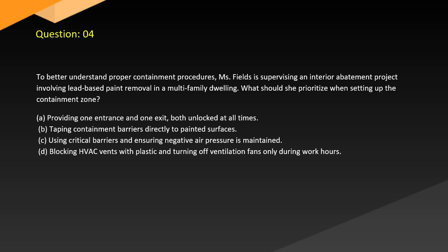Question 4. To better understand proper containment procedures, Ms. Fields is supervising an interior abatement project involving lead-based paint removal in a multifamily dwelling. What should she prioritize when setting up the containment zone? A. Providing one entrance and one exit, both unlocked at all times. B. Taping containment barriers directly to painted surfaces. C. Using critical barriers and ensuring negative air pressure is maintained. D. Blocking HVAC vents with plastic and turning off ventilation fans only during work hours.